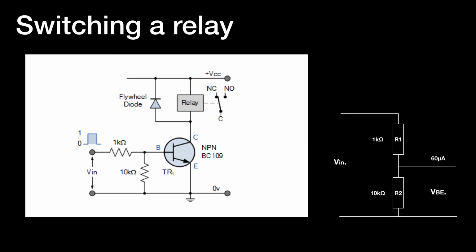So there is a practical circuit and a circuit we now are able to interpret and do some maths around to understand what's going on. We could look at the current gain, and we can look at the resistance or impedance presented to the signal.